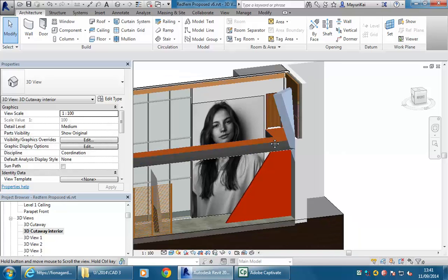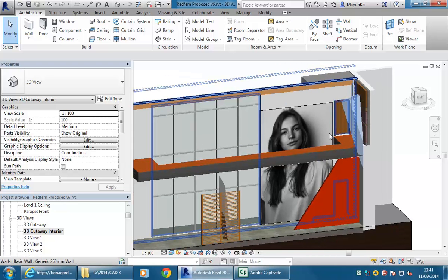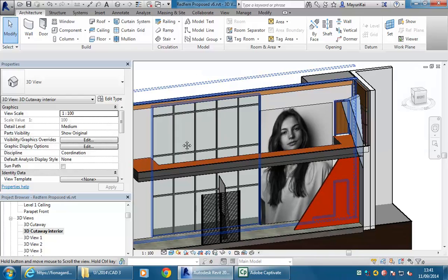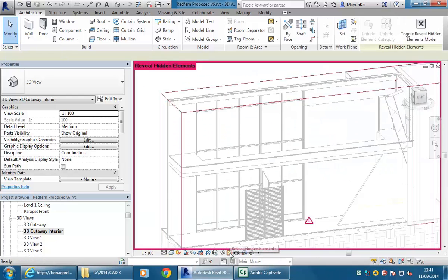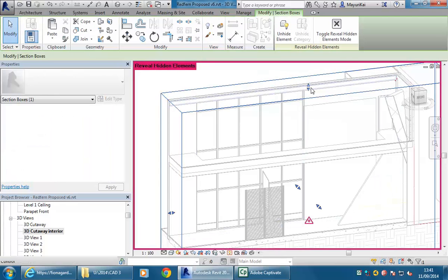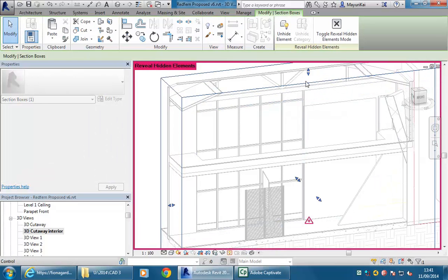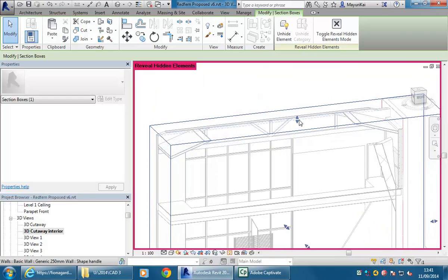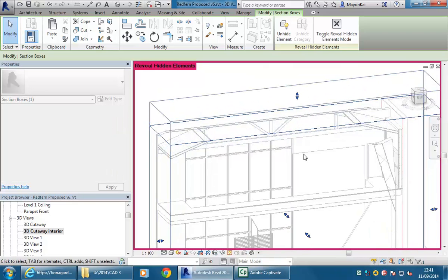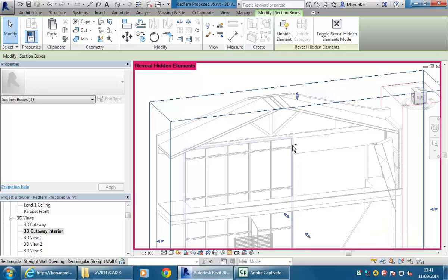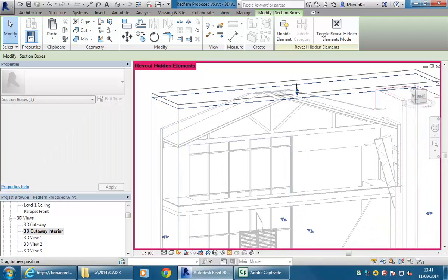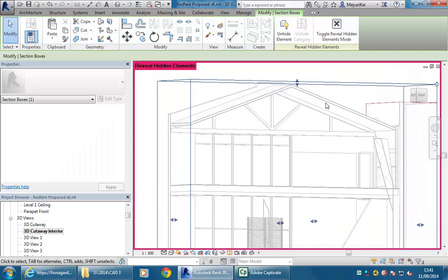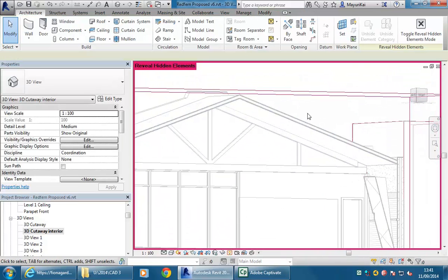okay, so here where I've got the view set up to work with that decal, I can, another little trick there, go to reveal mode, so I can adjust my section box without having to unhide it. I just want to bring it up so that I can see my ceiling. So I have a ceiling there on the underside of that roof. And so back to light bulb off.